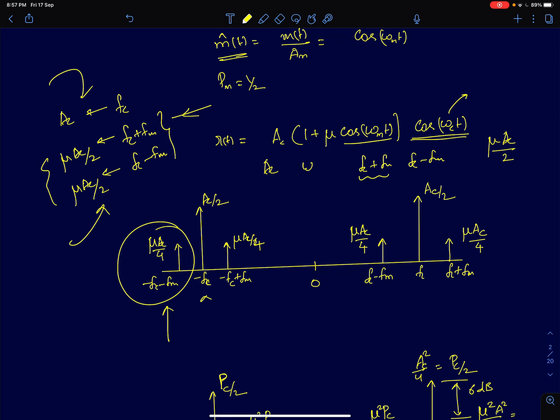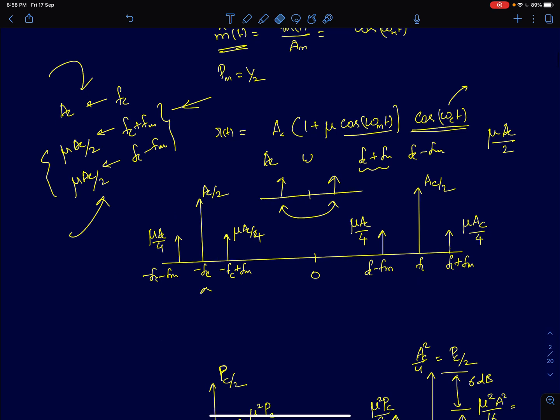Only the phase terms will differ, but since they are all real signals, at lower frequency they exhibit conjugate symmetry. Which means the positive and negative frequencies will be conjugate pairs. Therefore at higher frequency, when you upconvert it, the same condition holds true. So these two frequencies will be complex conjugates of each other. So that is something that will hold true. Okay. But when you talk about power spectral density, we don't have to worry about the phase.